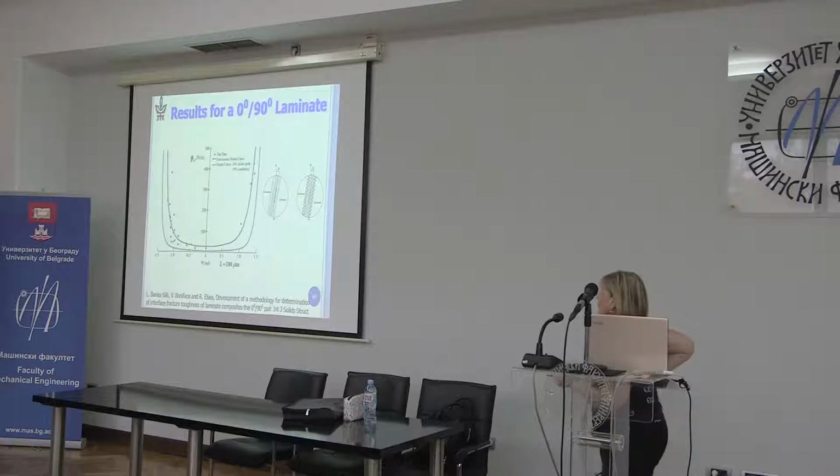So here are the results. The black curve is our deterministic curve. This is for the glass epoxy, this is for 0-90. You can see that G1C bar is 26.5, and we've worked on L in order to center our data. And really, you can see the data up here, how well it fits the failure curve. This data and the previous data, I didn't point it out with the glass epoxy, this data really is convincing that there's something to this failure curve because of how the data is sitting about it.